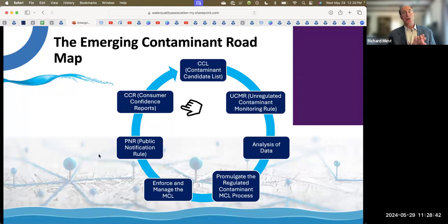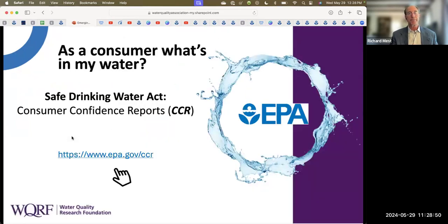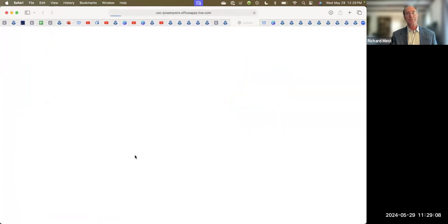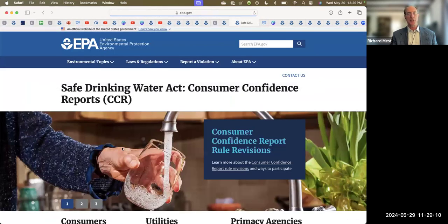Now, lastly, on the emerging contaminant journey is CCR, Consumer Confidence Report. Once a year, the EPA mandates that every public water system do a snapshot of water analytes so consumers understand with a broad brushstroke what they've been seeing in concentration in their water supply. And here's the link to that.